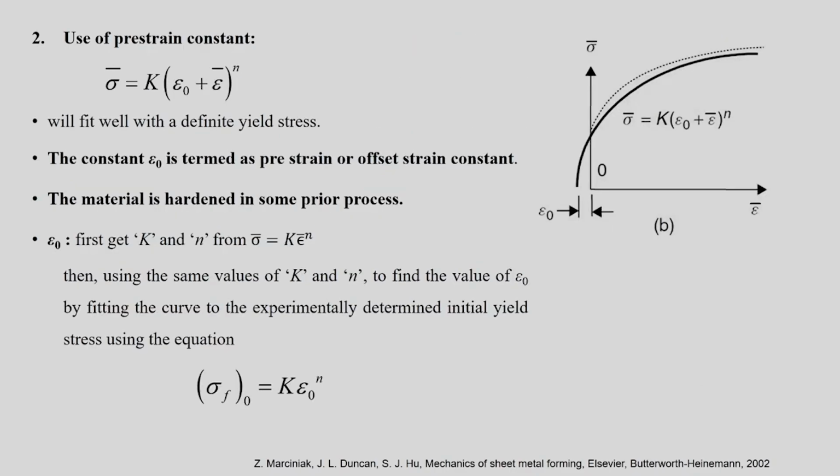Now, to capture the change in strength when you do a tensile test, you introduce something called a pre-strain. This is what we used in the previous problem as probably 0.008 or 0.0008. That's a small value we used. It's generally a small value. So now if you put epsilon bar as 0, you will see that there is a small effective stress staying with that material, and they may coincide somewhere here.